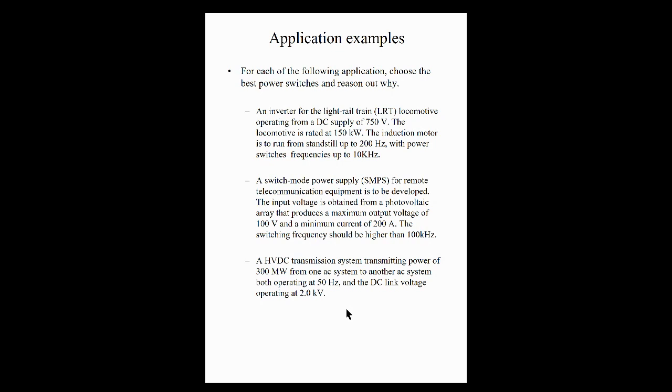The input voltage is obtained from a photovoltaic array that produces a maximum output voltage of 100 volts and a minimum current of 200 amperes. The switching frequency should be higher than 100 kilohertz. Right, so that's another scenario there where you're going to have to analyze and select your switch.